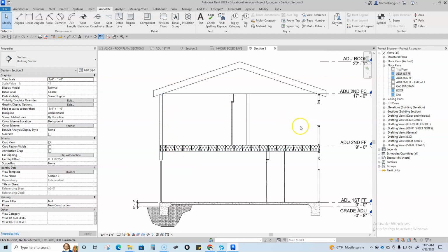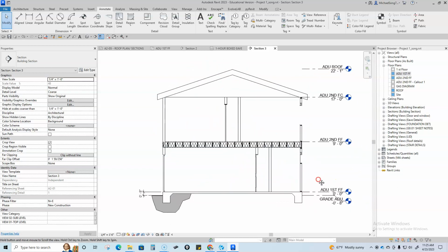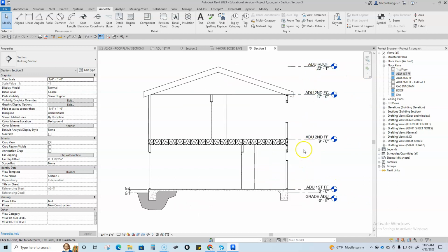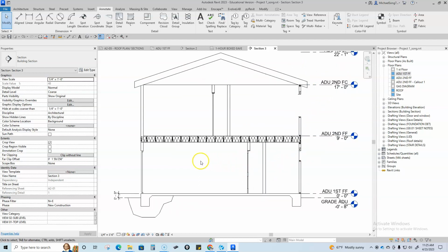But the width of the house should be drawn accurately, because that's what they're going to build out in the field. So you kind of have to know the difference between the symbol and when you have to draw things dimensionally accurately. Most of the section parts are symbolic in nature, except for the vertical dimensions. Those are pretty solid.